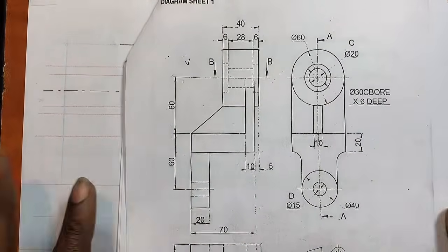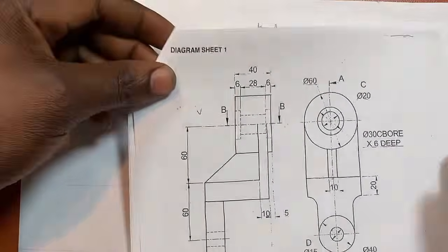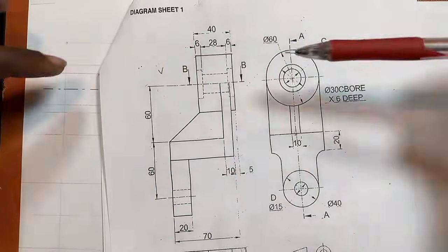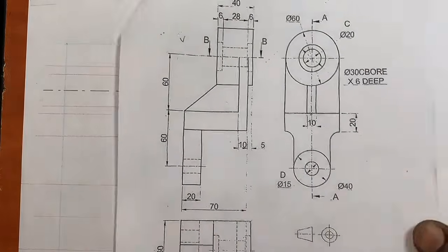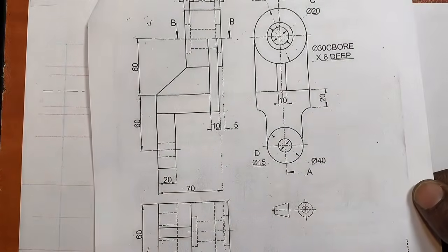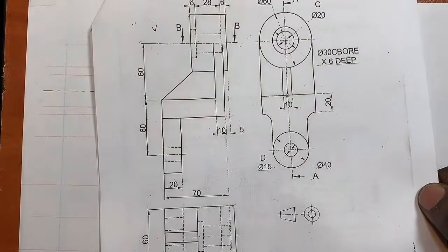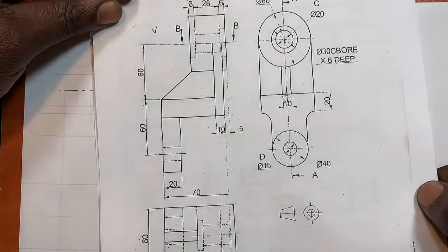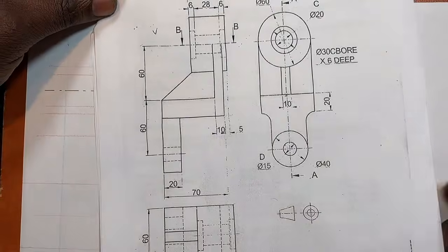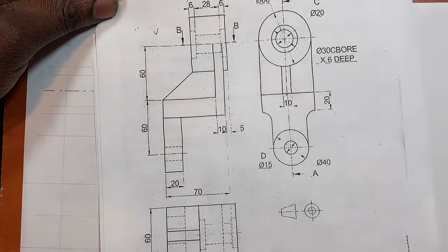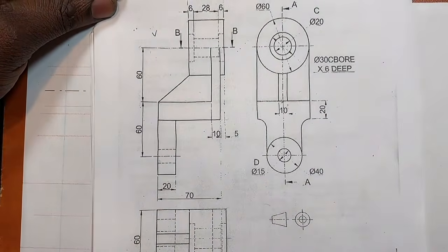Do you see how we started it? We didn't start by drawing the front. As much as it can look like you have to simply start with the front. You understand? So while we are drawing the front, we are also tracing the cutting plane, so that those lines that are going to disappear, we don't even draw them.